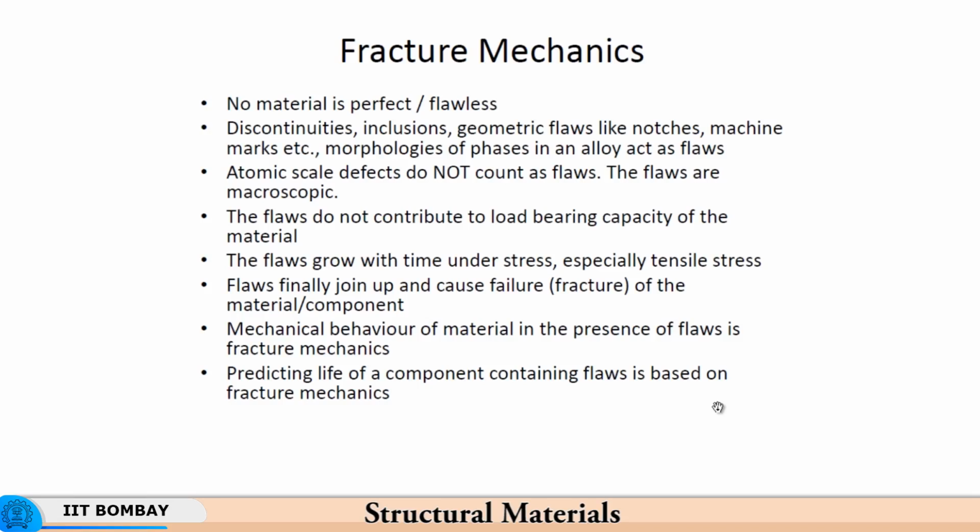So, we do not wait until the flaws have come together and have formed a crack to finally cause separation, but we would say that once the flaws have grown to a certain percentage, we scrap the component, we discard the component.